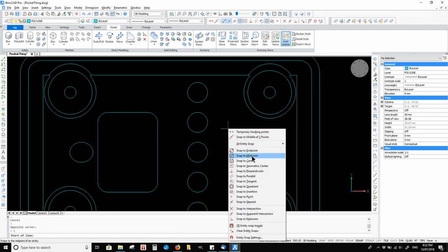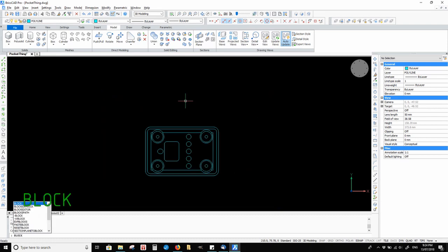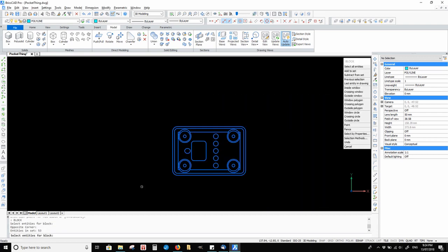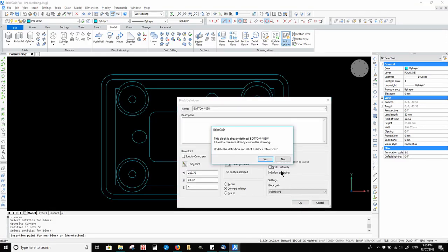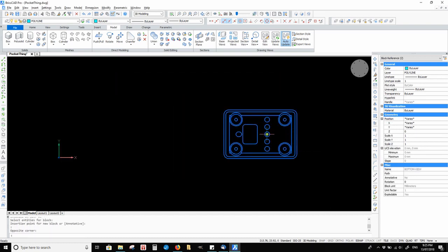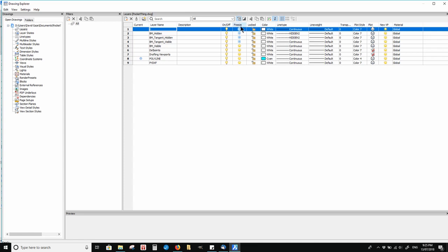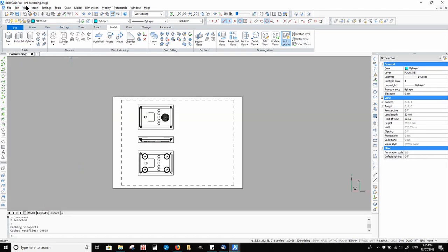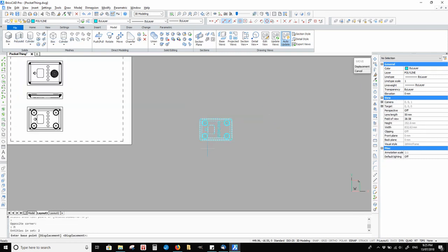Test that we can snap to center. Turn our drawing into a block. We'll use it a few times. We can now use our block in paper space to find circle centers if we want to take sections through them. We'll only do a section down the middle, but you could do multiple sections if you wanted.